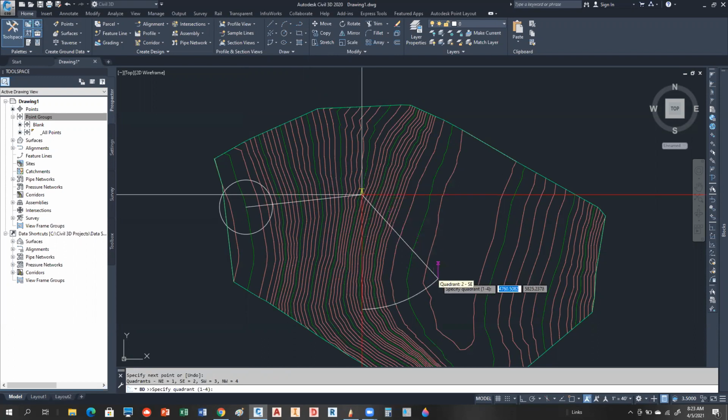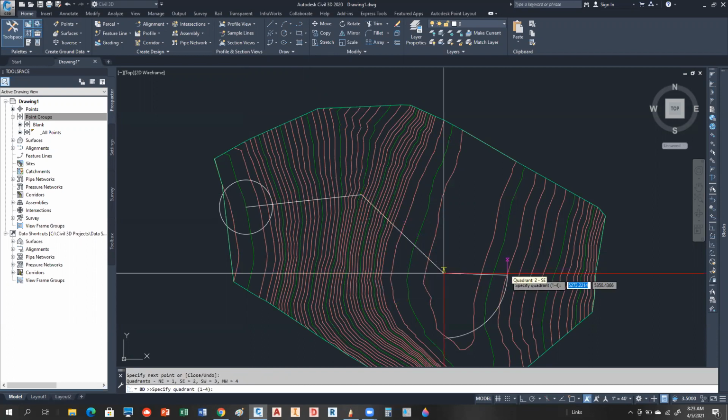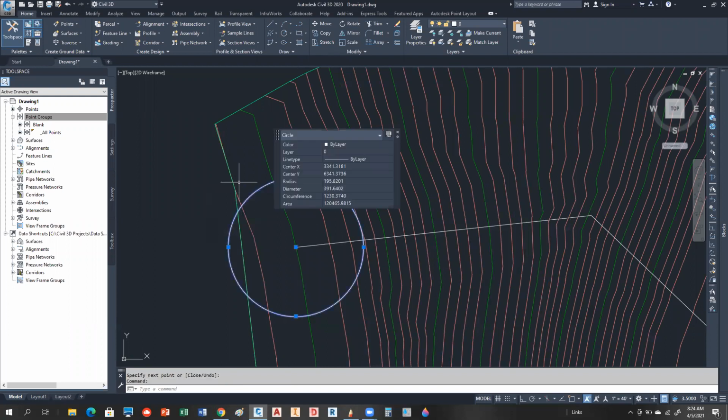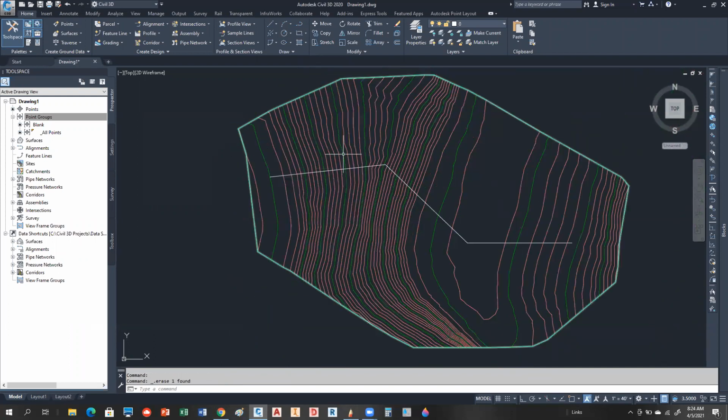And then we're going to go into the southeast quadrant, 2, 47 degrees at 830 feet. And then at the end of our road, it's going to be due east, 90 degrees, I think, 775. And then you're done. Okay, so that's going to be our alignment. And the circle really has no more relevance to us, so we can just delete that out now. Is everybody okay?